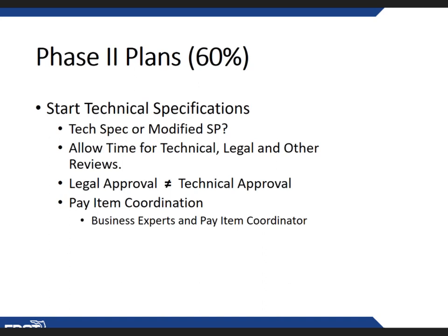we go down, and again, if it's something that a product that multiple manufacturers can meet your specification, then the question is, why are we not using a standard product? DOT's been building roads for quite a while now, that we've got most materials and situations covered. But what is unique about your project that the normal drainage inlet won't work? And just because a designer wants to be creative is not a good reason for doing something non-standard.